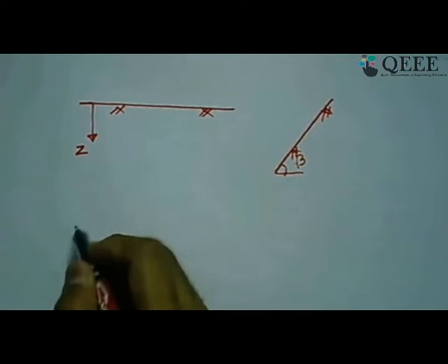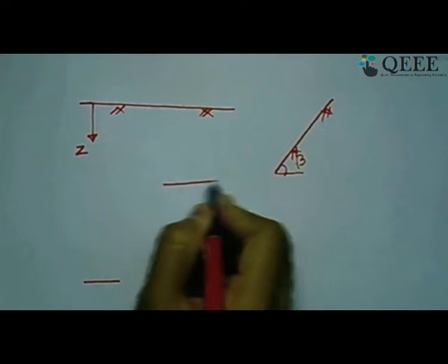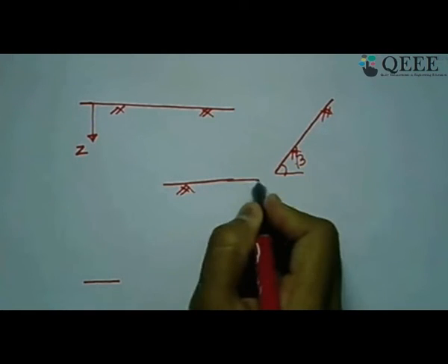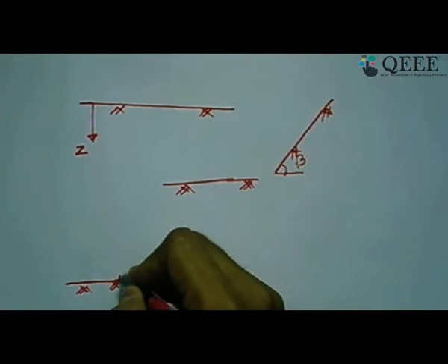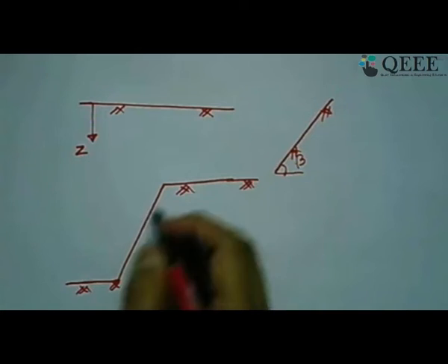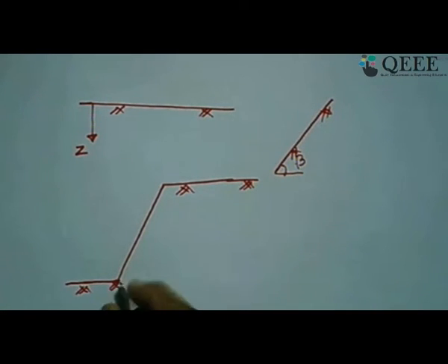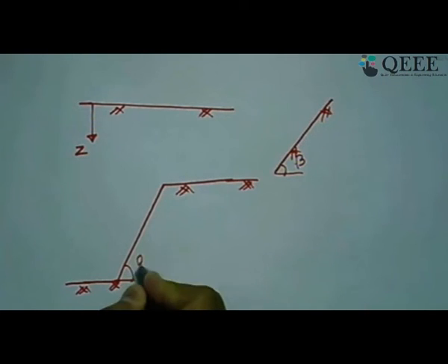So whenever we want to have some kind of level difference in the ground, suppose my ground surface at one side is like this and another side is like this, we can achieve it by means of a slope like this. But this slope, or this inclination which maintains the two different levels of the ground surface, has to be stable, provided this angle of inclination is very shallow, considering the soil properties.